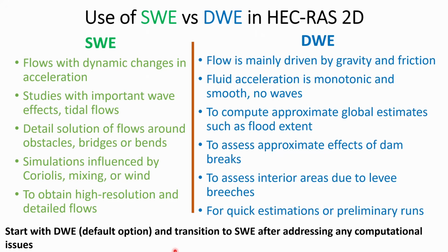The final question you may wonder is what to use. Should I use shallow water equation or diffusive wave equation? Now I'm not going to read everything that you see on the slide. As I mentioned earlier, DWE is the default. Now even if you are going to perform a very complex simulation where you have backwater flow and tidal effects and things like that, you do want to use shallow water equation, but it is always a good practice to start with diffusive wave equation.